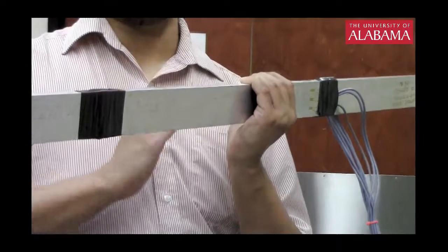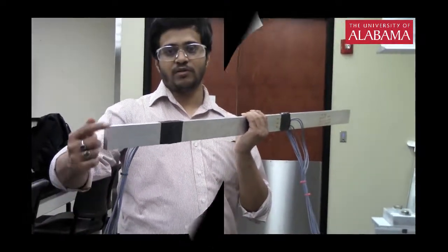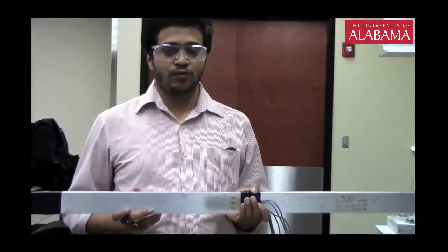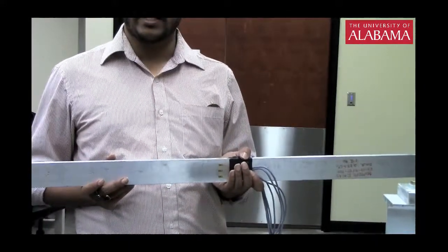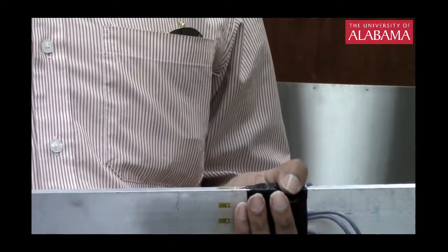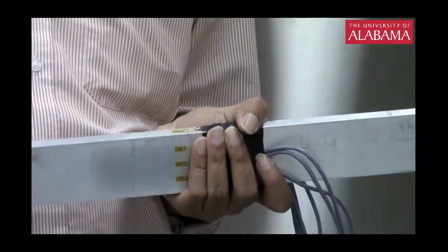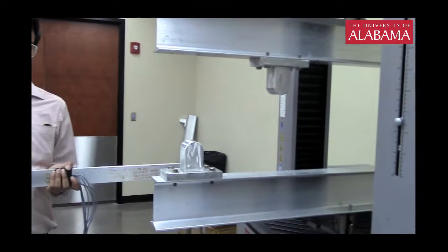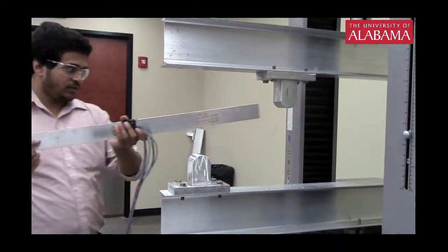Okay, and we are going to find this out from the experiment which we will do today, and also from theory. We have a total of 9 gauges, and these strain gauges are exactly similar to the strain gauges which we used for the Poisson's ratio test. Since we have 9 gauges, we need 9 channels in the strain gauge indicator, that is these blue boxes, to measure this strain. So what I'm going to do is set up this beam first in this frame over here, then explain to you about the frame a little bit, and then I'm going to come and show you the strain gauge indicators.